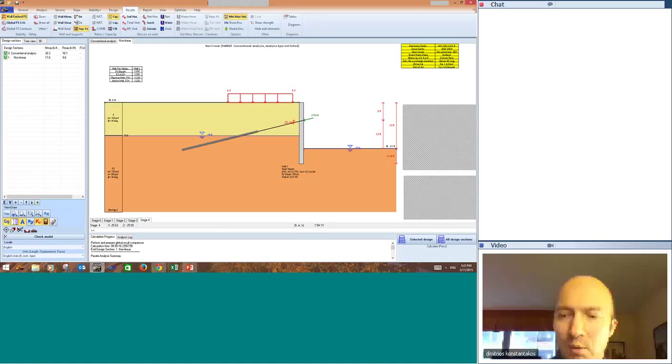It's nice to be a little bit extra safe with wall embedment. If you over excavate, you don't have any other means of holding that wall there. So I want to see if there were any questions so far on this part. Okay, I don't have any questions yet.